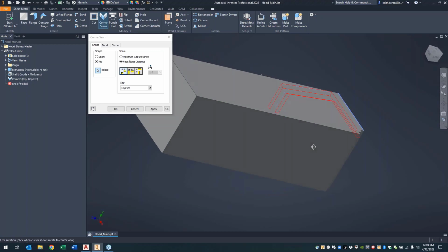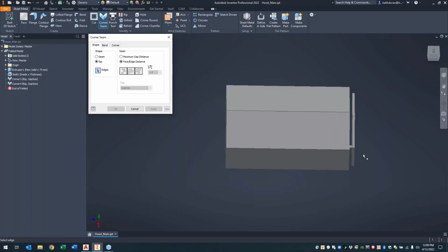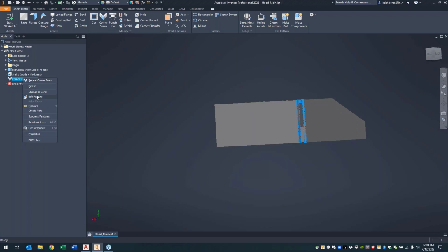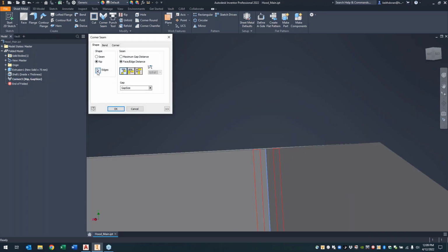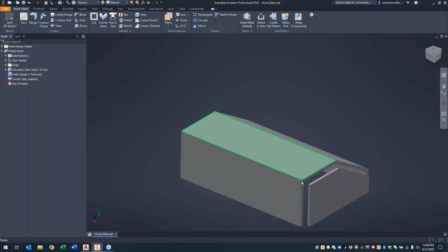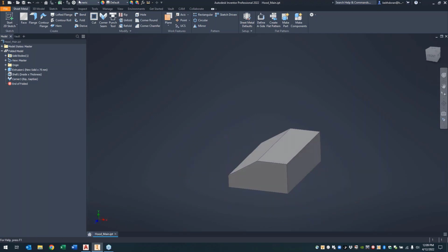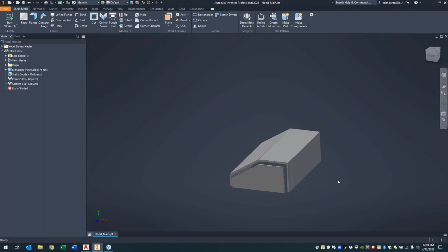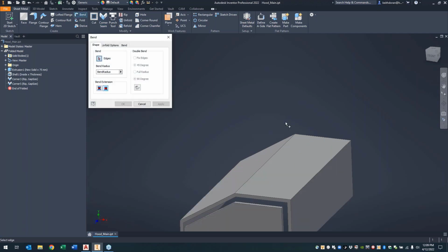all at once, it's going to clean up that boundary all the way around. In my case, I didn't edit the existing one. So edit that and select all my edges. We can get a clean separation between those components. I'll repeat the process on the other side. And then from here, using my bend tool again, in this case, I need to reconnect these two elements. So I'm simply going to select the two outer boundaries.